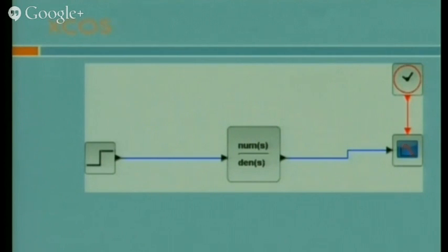On the command window, type Xcos and the windows will be opened. Two windows will be opened. One is the palette window and the second is the graphic window on which you make your blocks. Same as in MATLAB.